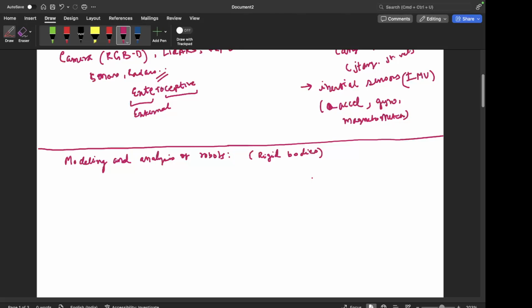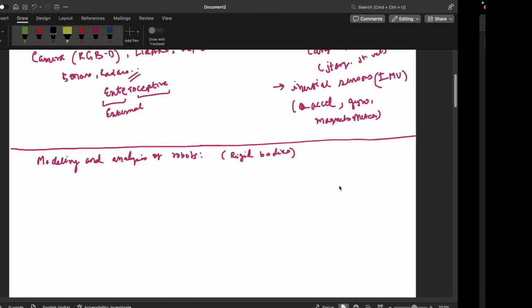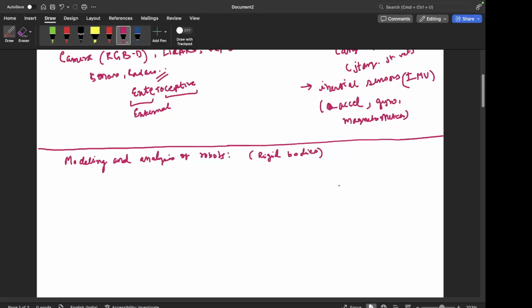This is known as calibration. So we have to specify that this is my zero position of the joint, and once that zero position is recorded, then how much we have moved in what direction is given by the relative encoder. So, Siddharth, let me know if I have briefly cleared your doubts.